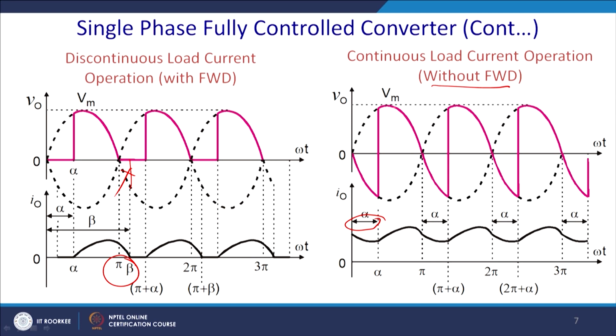Then the thyristor will be triggered at an angle alpha, so you will get forward voltage across the load. Then the thyristor is in a forward conduction mode due to the high current, and ultimately it will deliver negative load voltage. Similarly it will continue. So, negative load voltage can be truncated with the use of the freewheeling diode.